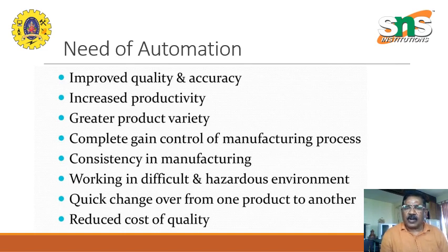Quick changeover from one product to another. If I'm having a machining being done, and once it is over, I have to change to another component. Single minute exchange of die, SMED, those things all come up here. In one minute I just take this out and put the other one, so that the downtime is as little as possible and the productivity really goes up. We look at more about the flexibility in changing over from one component to the other, which is not productive time. The lead time is to be shortened as much as possible.